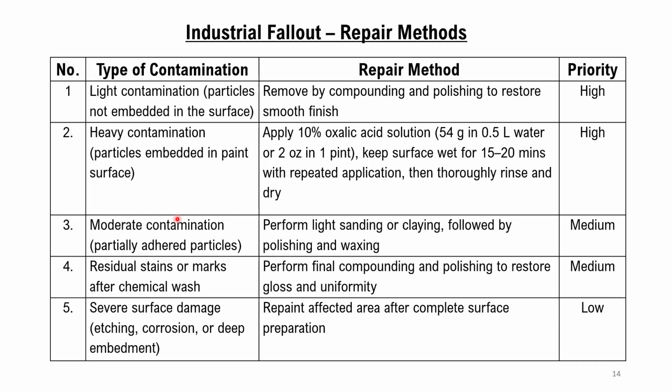Or in case of moderate contamination, perform light sanding or claying, followed by polishing and waxing. Perform final compounding and polishing to restore gloss and uniformity. Repaint affected area after complete surface preparation. So the solution depends upon whether the contamination is light or moderate or heavy.